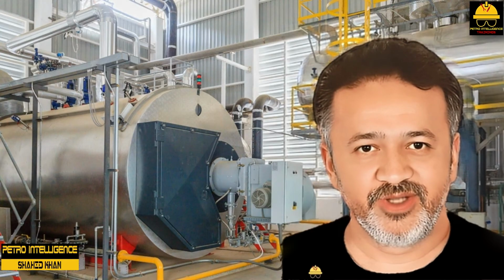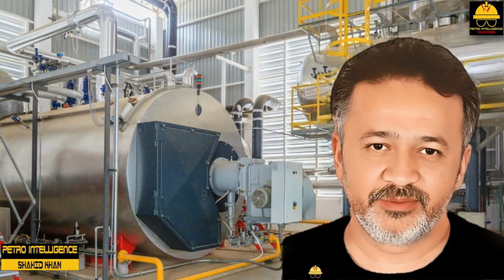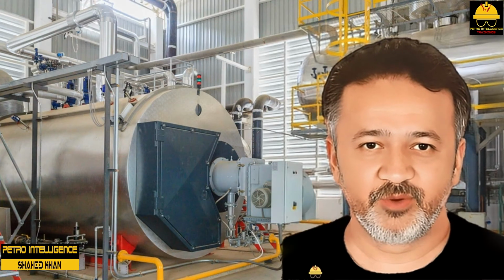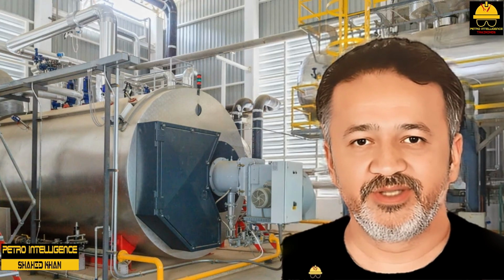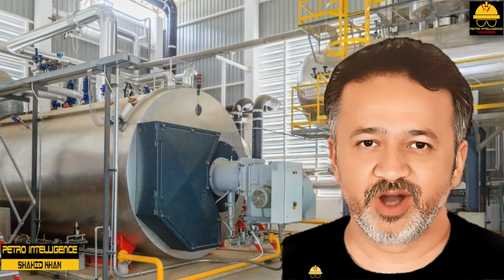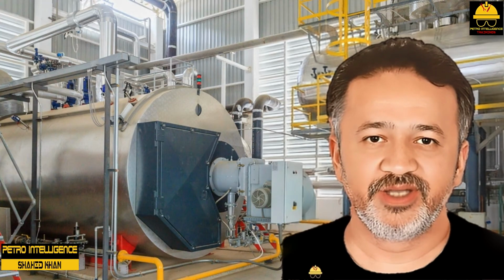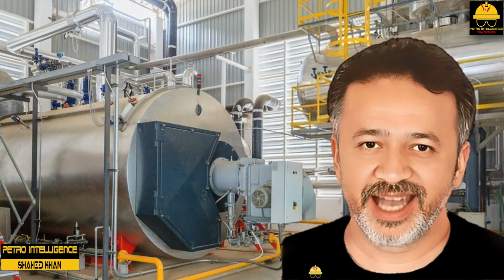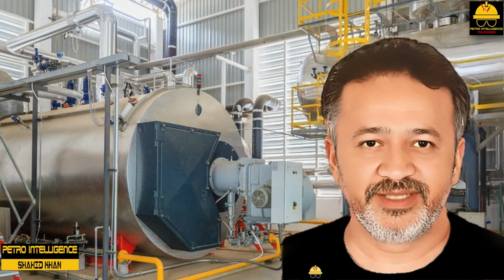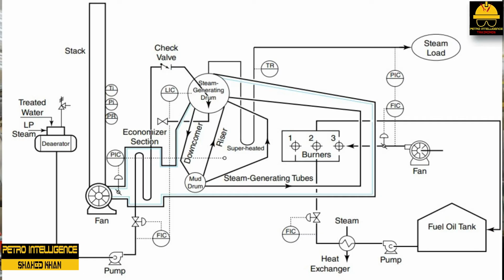Condensate can cause many serious problems as it flows with the steam. Slugs of water can damage equipment and lead to a condition known as water hammer. Devices known as steam traps are used to remove condensate. Steam traps are grouped into two categories, mechanical and thermostatic. Mechanical steam traps include inverted buckets and floats. Thermostatic traps include bellows-type traps. A steam system that includes a steam trap is shown in picture. Inverted bucket steam trap.